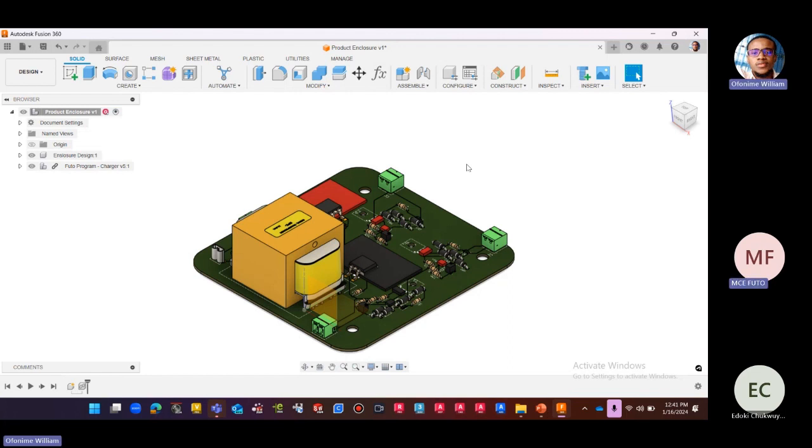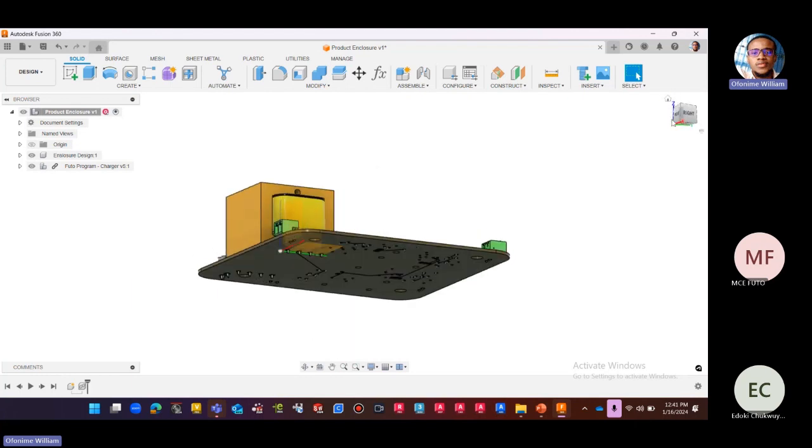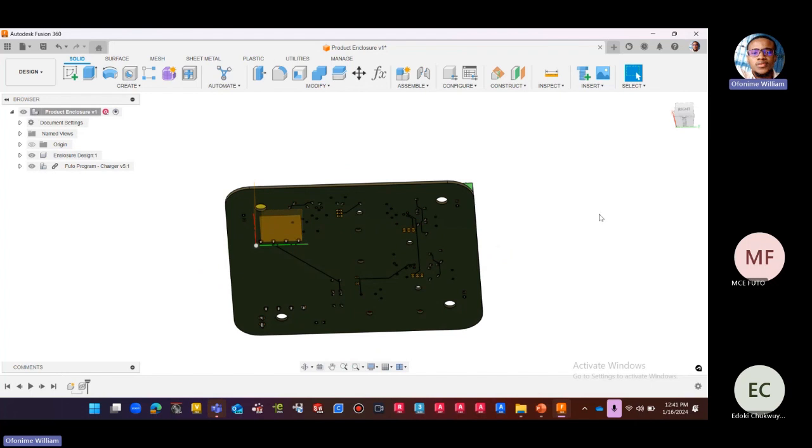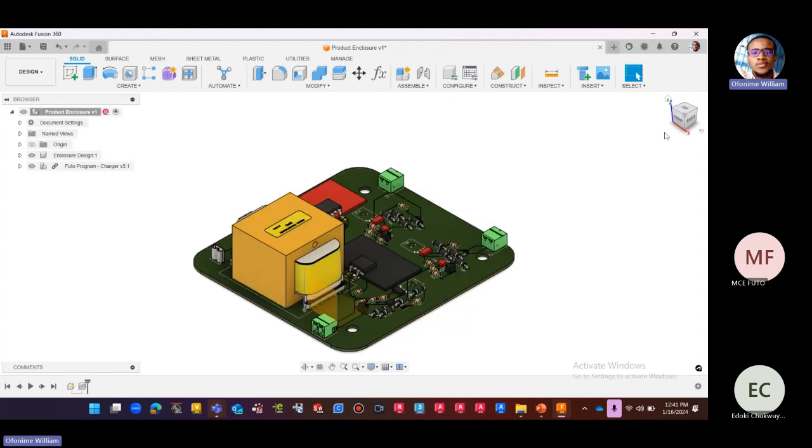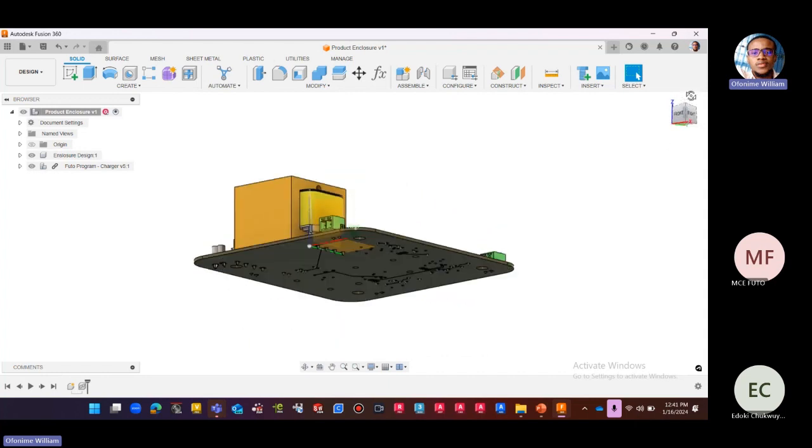All right. So now with the parameters created, the first thing I will want to do is to have a plane. I talked about a plane earlier on, and I said you want to draw, but you have to draw on something. So assuming your lines are the things you're using to sketch, as your pen or pencil, you now need a place to do your drawings on. So you can simply understand a plane as your whiteboard or your drawing board.